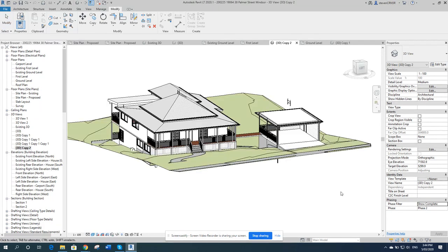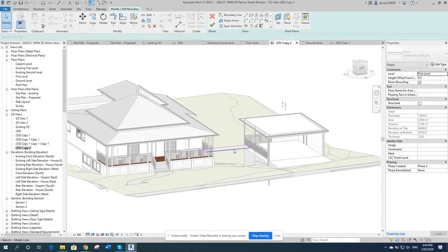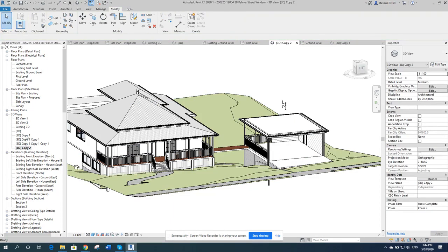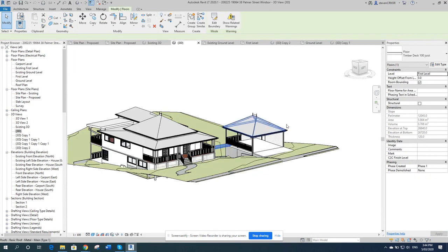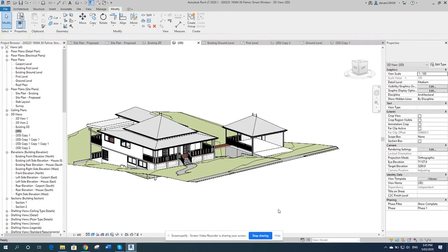There is a way that you can, so if you wanted that, you drew that and you drew it in the wrong phase, you can just change it at any time over here. So then you go back and then that's in that phase. So even with the demolition, you go, okay, well, I don't want to demolish that. So you just go to none to bring it back if they've changed their mind about it. So that's how we use it a lot.